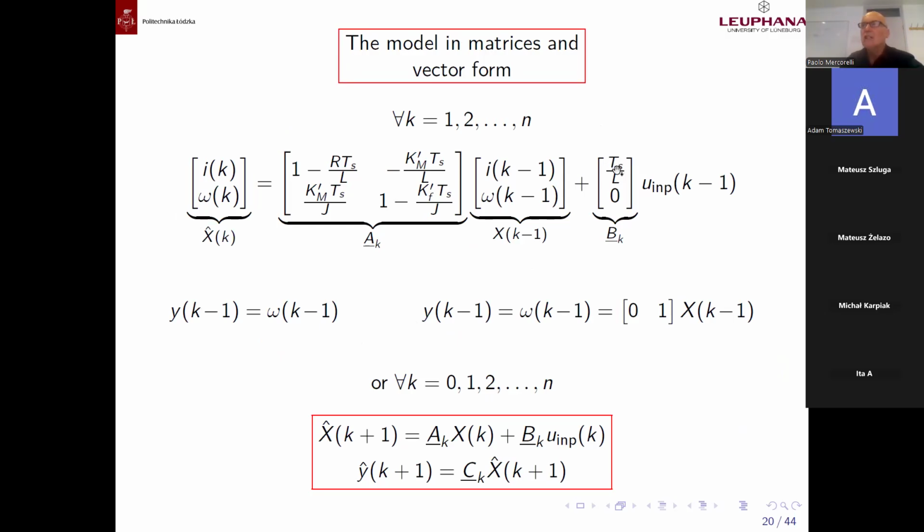Also here Ts. I should remark that Ts plays an important role, because if Ts is too small, remember I told you we end up not controllable, because if Ts is very small, we don't have the possibility to control the system in its representation, in the microcontroller. This means we cannot use it, or it is almost not controllable, if Ts is too small. And here, if Ts is too small, again, we lose not only the controllability, but also the observability. About the observability, I will tell you later. Why that? Because we have here 0, here 0, here 0.